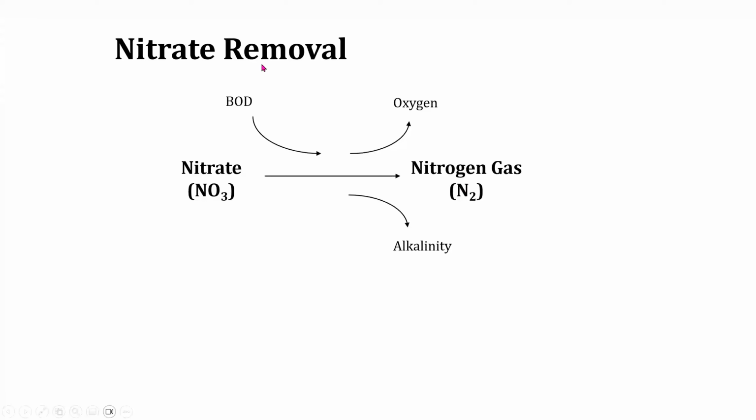Now, I mentioned, I think, in my phosphorus discussion that the organisms that denitrify, they're not very fussy eaters. They're kind of brutes, so they outcompete the phosphorus organisms, and they'll eat most any form of soluble BOD, but they prefer the volatile fatty acids, the candy that the phosphorus organisms, the one and only thing they'll eat.